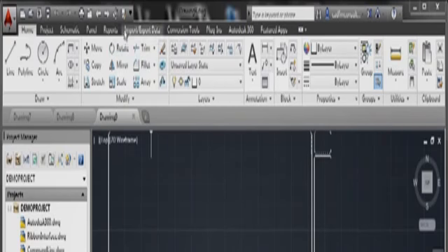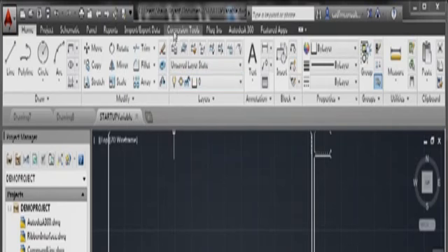What I'll do now is go up to Save As, and I'm going to save that as Startup Variable. I'm going to put that in capitals to show it's a variable, and then I'll type that in there, Startup Variable. Notice it's defaulted to that 2010 drawing that we set up in the options earlier. I'll click on Save there. That's now saved. You can see the path. Now, if you've got a big long path like that, just click on Save here, not Save As, and then all it does is show the file name. Just a little bit easier when you're trying to work out what your file's called.